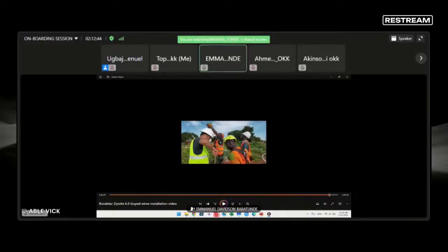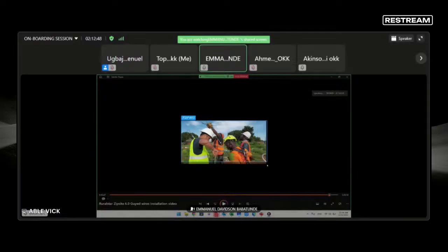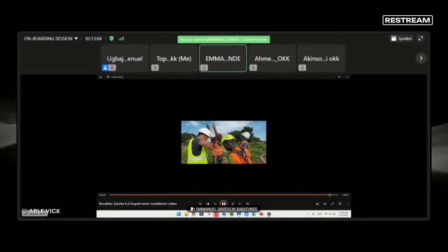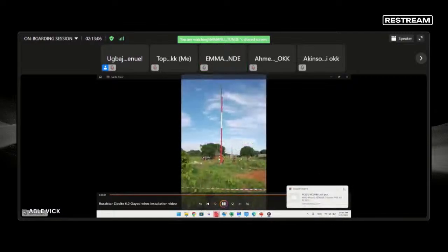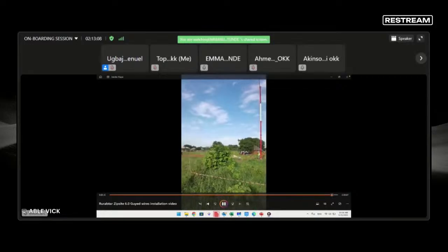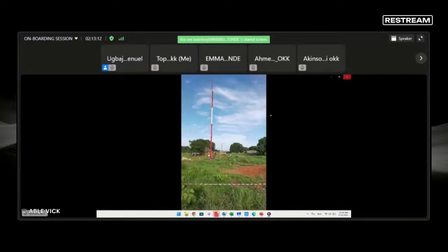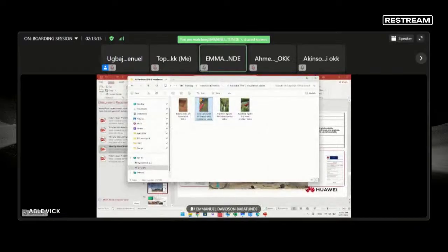Like you can see at the top here, you can see how they wrap some excess around here. You can see it's excess that they wrapped. So wrap your excess and clip it to the wire. You don't need to cut the excess, leave it there on the wire. Just wrap it, tidy it up. So that's for the guide wire installation, right?